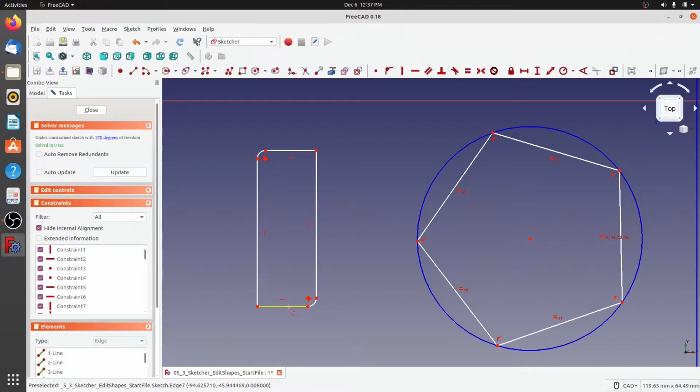Now just watch carefully. I'll demonstrate on this side of the edge. So I want to create a fillet on this angle here. The first point that I select is more than 50% of this line segment here. So I've selected this line segment, and for this line segment I'm again clicking more than 50% of the length of that line segment. As you can see, the fillet has been created, but it just changed the entire geometry.